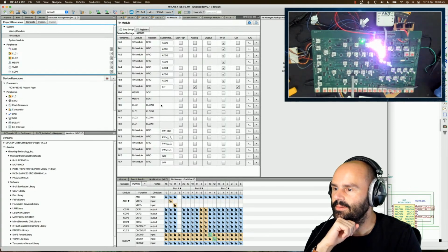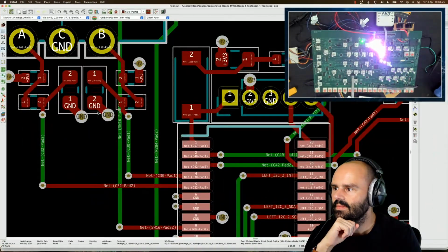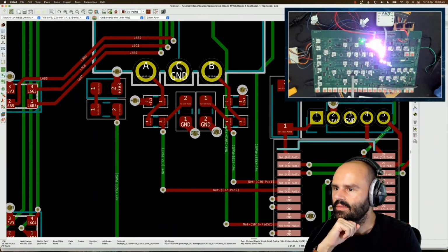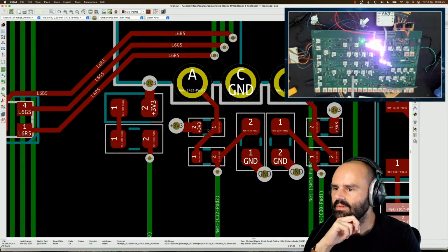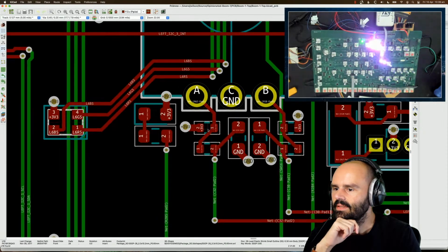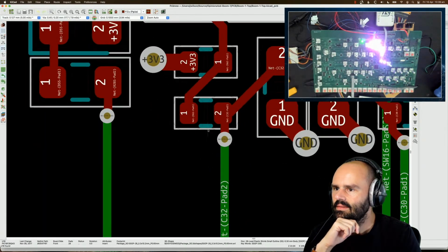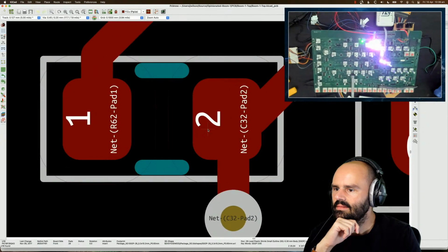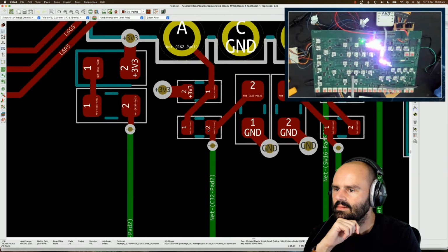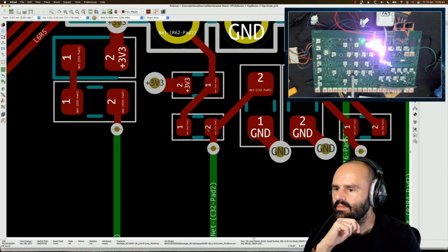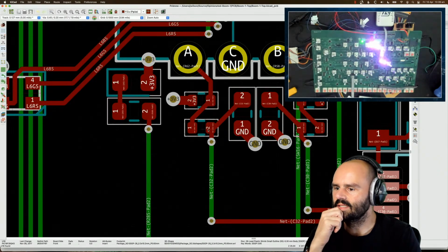What have we done wrong? We got ground signal on this. This is exactly like we did it on the breadboard. Alright, we have a pull up on there. We've got our RC combo just doing a little bit of a filter, cut out the jitter.